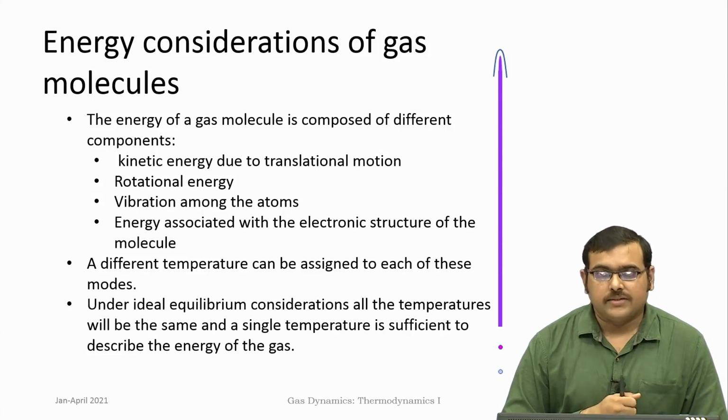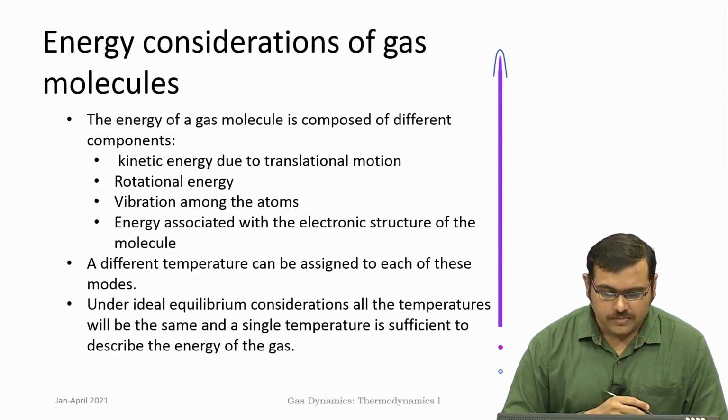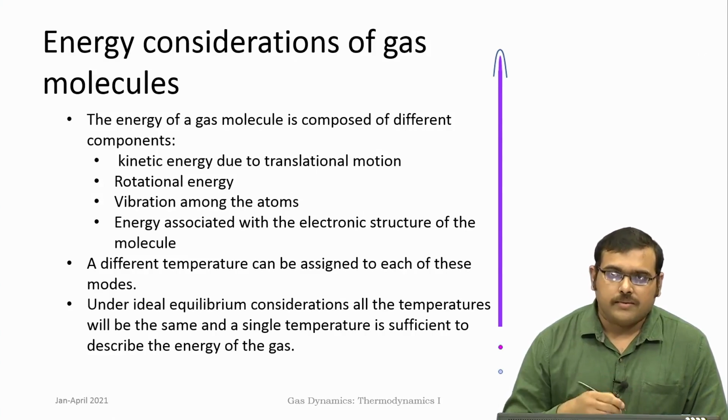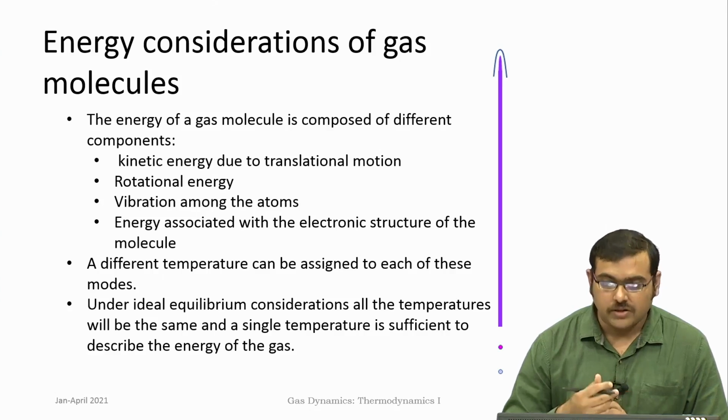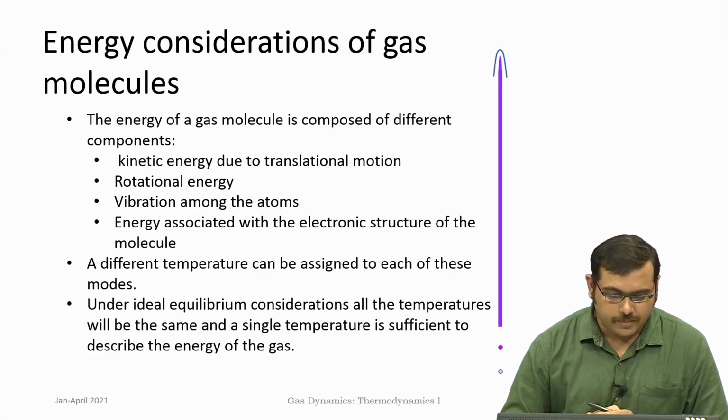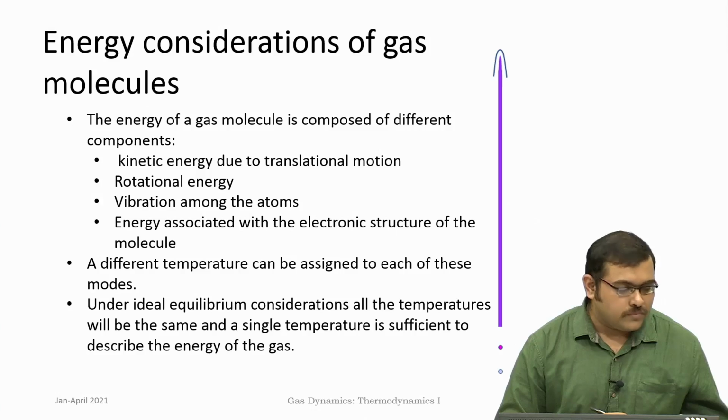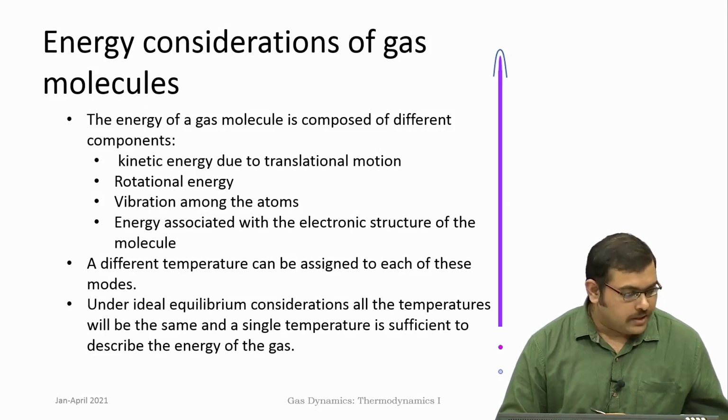In many cases in compressible flows, particularly at much higher speeds, the temperature can increase so much that other modes of energy become more excited than the rest, then we will have differences, and the consequence of that is changes to the specific heats of the gases.